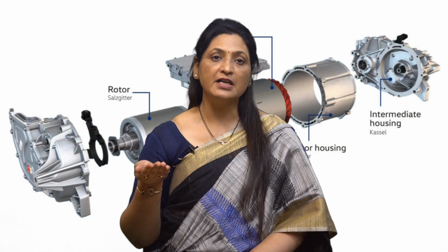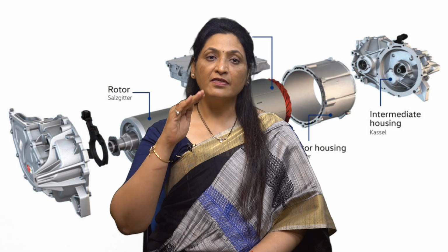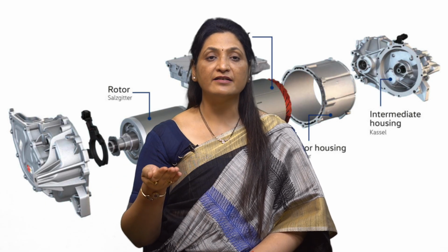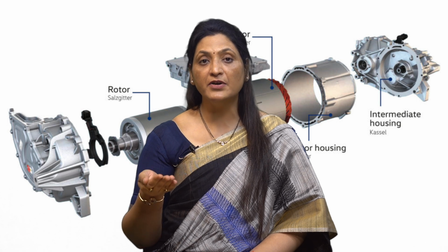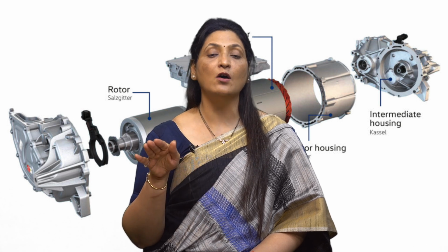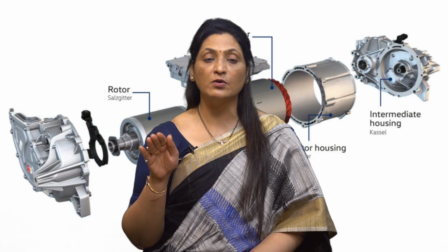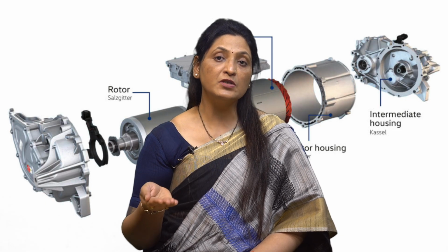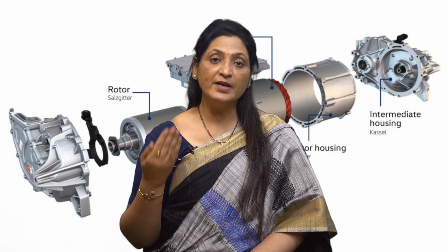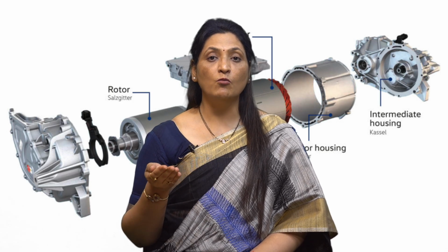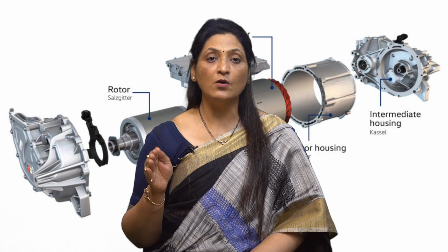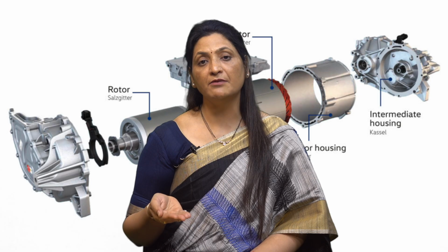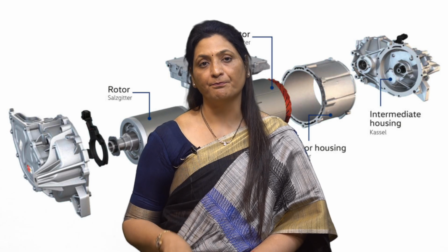The second one is continuous maximum rating. The continuous maximum rating refers to the highest power output that the motor can sustain indefinitely without exceeding the overload capacity. Here we cannot overload the machine. So, this is the output which the motor can give continuously for a long time without exceeding the temperature rise. The motor cannot give any overload and is used for motors of size larger than 25 HP per RPM.